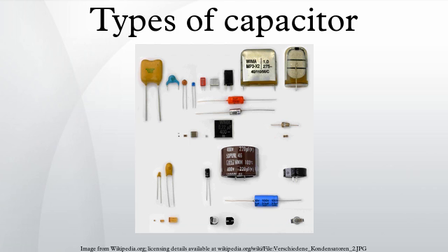The relatively high capacitance value of an electrolytic capacitor combined with the very low ESR of the polymer electrolyte of polymer capacitors, especially in SMD styles, makes them a competitor to MLC chip capacitors in personal computer power supplies.